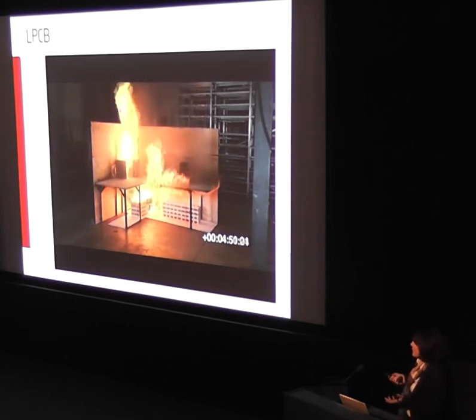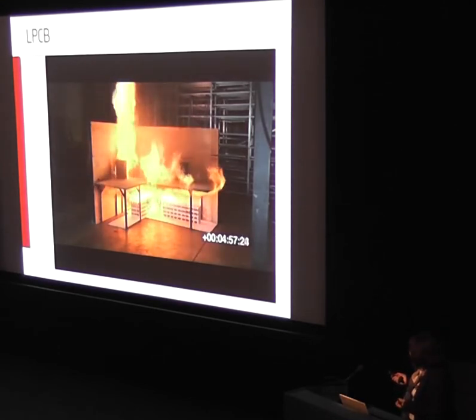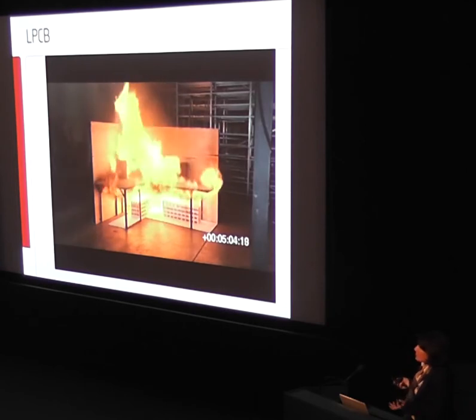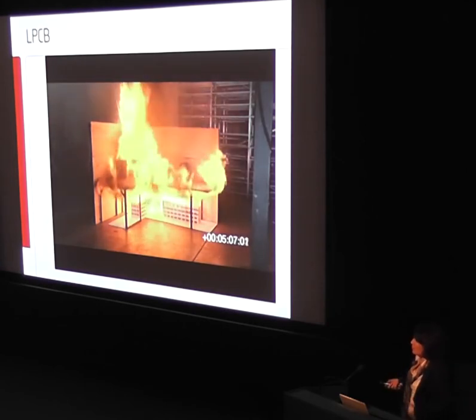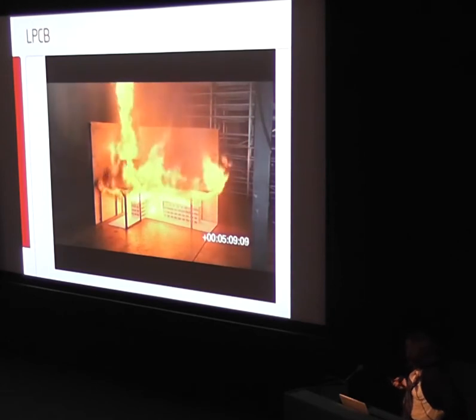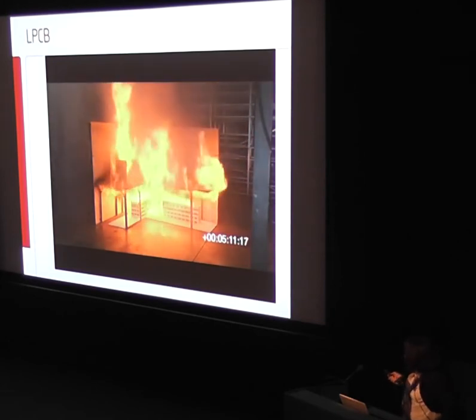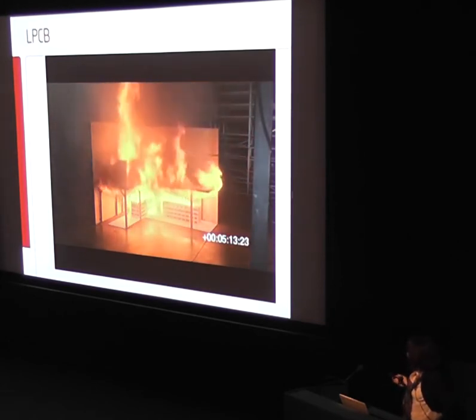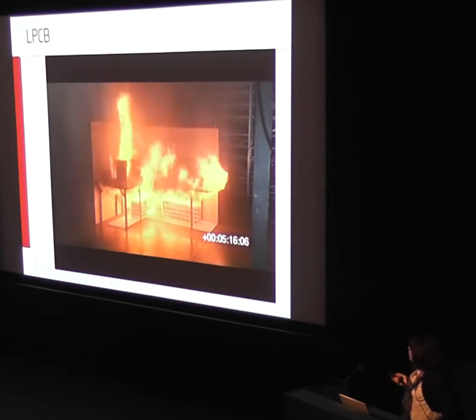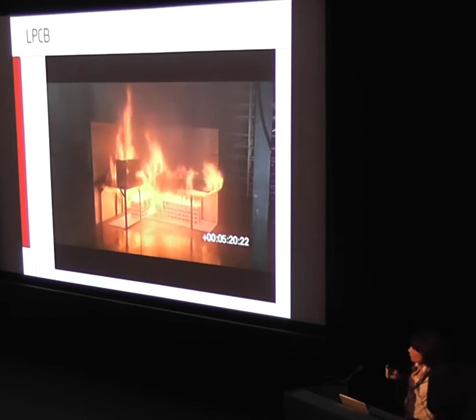We had thought that the sprinklers might have operated a little earlier, and so we've got the polypropylene burning on the top of the crib. Our plan to see if we could prevent a spread across some of it was negated by the slowness of the operation of this system. At this point, you can see the mist coming down now. The ignition source was in the middle of 4 nozzles, and all 4 are delivering onto our ignition source.